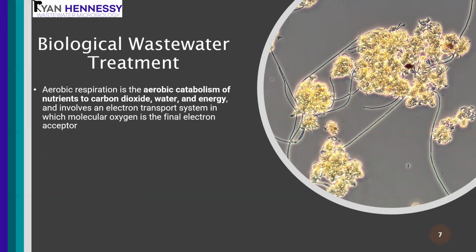So biological wastewater treatment, the general goal is that when we have aerobic respiration, we're taking nutrients and the food, the BOD, to carbon dioxide, water, and energy, and it involves an electron transport system using molecular oxygen as the final electron acceptor. So for an aerobic reaction, you need free dissolved oxygen to exist. And when we talk about nitrification, the nitrifiers are strict aerobes, so they need free dissolved oxygen in order to work.